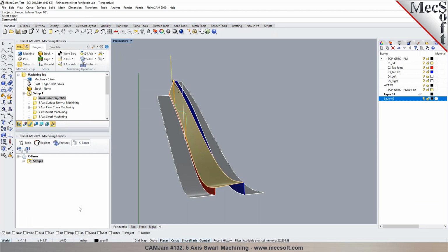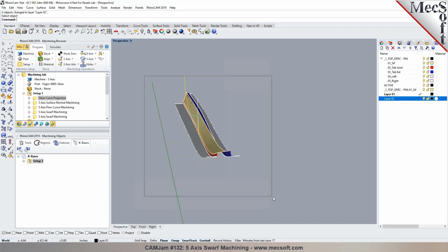Yeah, I'm just thinking we have this model that we're looking at, but it's maybe 50 different geometries. Mm-hmm. I'm just thinking of ways where we can automate that process. Okay. Yeah, you can probably structure it in Rhino so they're all in the same layer. And then you can even just make that layer visible and drag a window to select all of them when the selection dialog is invoked. Or you can right click on the layer and say select objects.